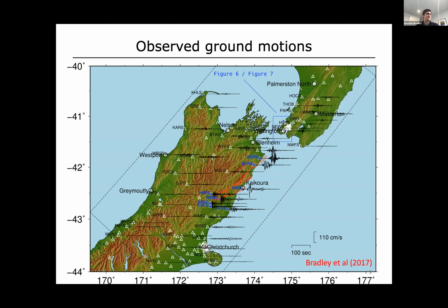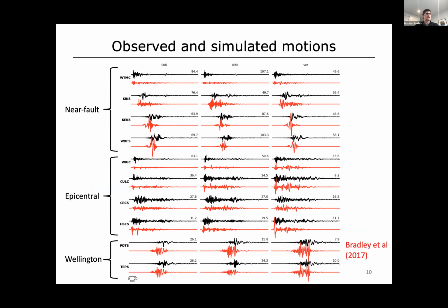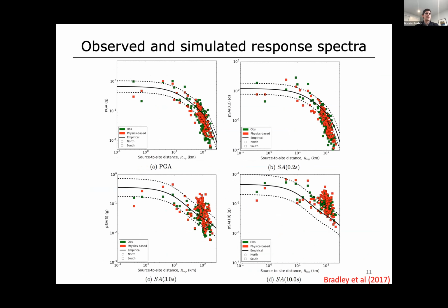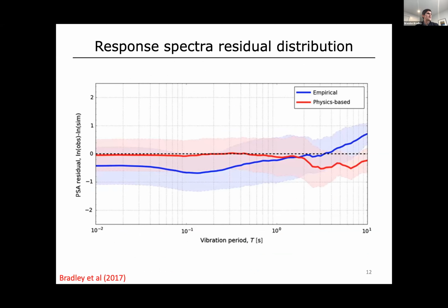Of course, for these types of historical events, we can compare with observed waveforms that have been recorded at strong motion instruments, either in a qualitative sense to gain insight, or in a quantitative sense by looking at one or more intensity measures and trying to determine directly, by residuals, the prediction versus observation differences. So we might see these very common summary plots, and for example, several of the last 3 presenters showed plots like this: residuals, both in terms of the mean across all sites, as well as some measure of the variation in those residuals from site to site.